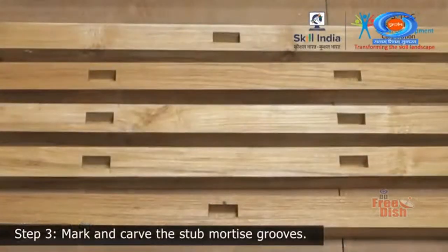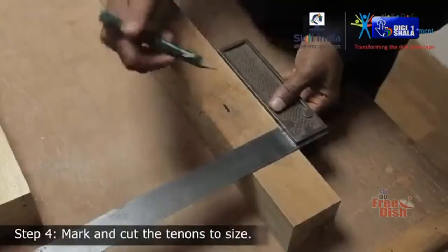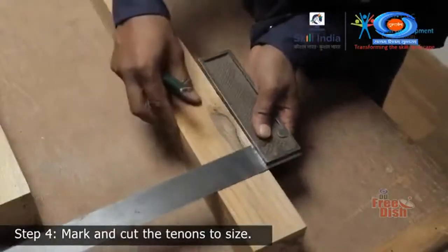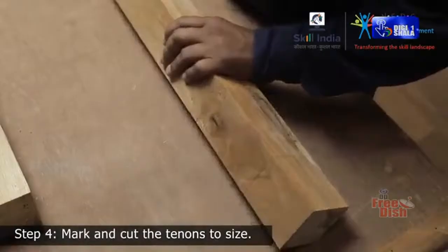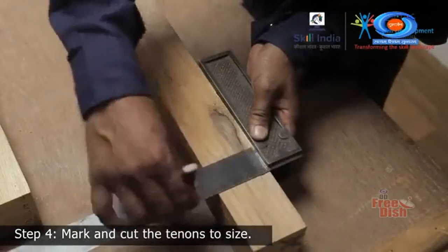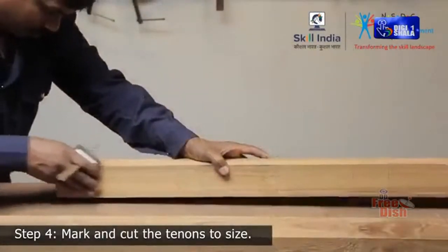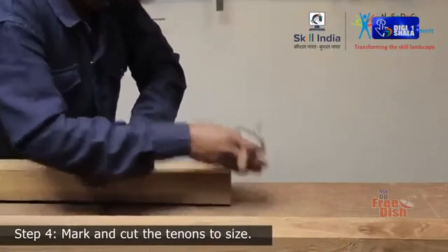Now that you have done all the mortise grooves, you need to work on the tenons to complete the mortise and tenon joints. Step 4. Mark and cut the tenons to size. Measure and mark the tenon length from the edge of one end of the piece and scribe the shoulder lines around all the edges. Adjust the mortise gauge to the center and scribe a parallel line for the width of the tenons.